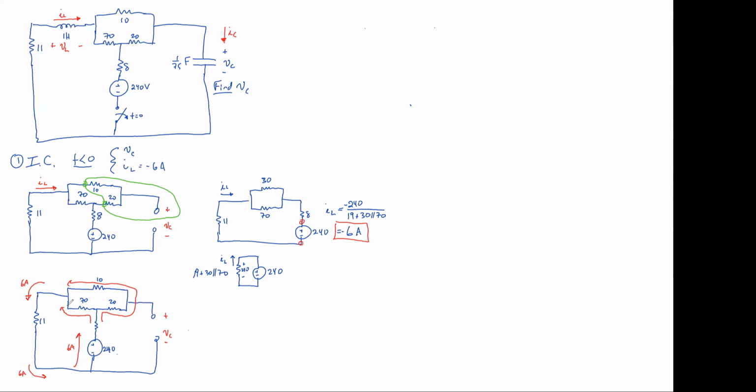I mean, just by inspection, we can see that this is 66 volts. And we can see that this enters more positive, exits more negative. Let's see, I think we said that the value of that resistor is 8 ohms. So therefore, this has to be 8 times 6 or 48 volts. If we knew how much current was going through the 20 ohm, we'd have this problem licked.